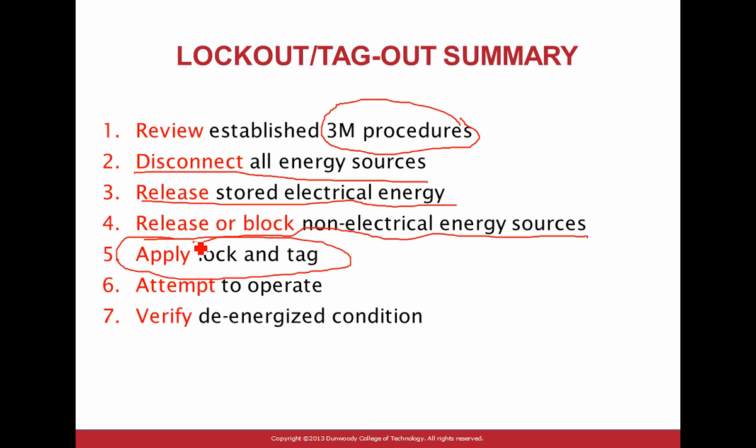There's a procedure, guys. What happens if you forgot your lock here and they want to energize the object and you went home? People do that. So the manager has to come, investigate, and verify that you're not in the process, go to the equipment, see nobody's working on it, and your manager has to sign it, then they go cut your lock. So you want to make sure that you are accounted for before somebody goes and messes around with your lock when you put your lock here. And I don't have a lock and a tag. You tag and lock it.